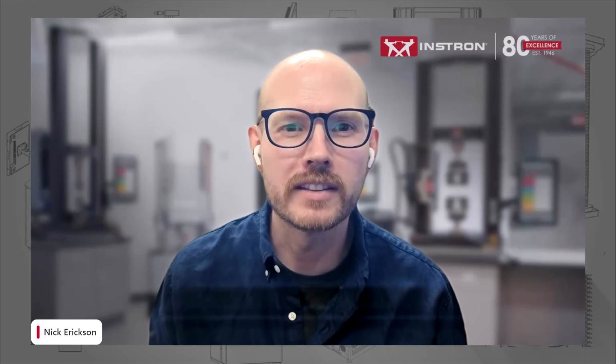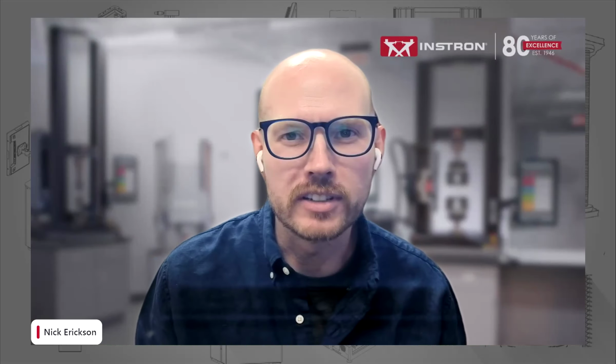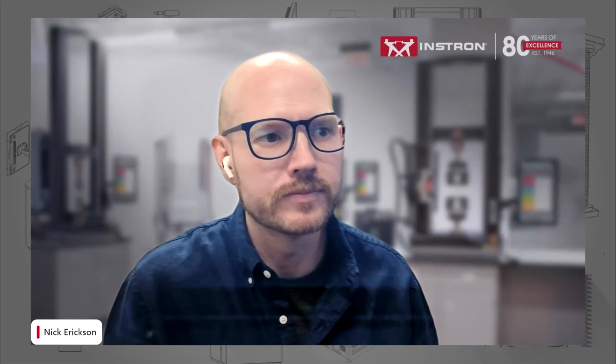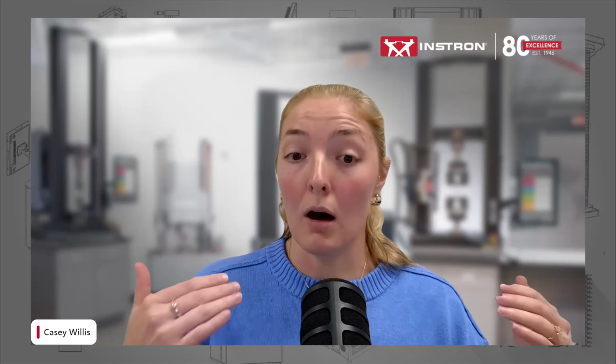Great. Next question we've got here is, what has been the best practice you have found for dealing with reflective materials being tested with the video extensometer? Yep. So it depends on what extensometer again that you're using. Maybe Josh can speak to this a little bit after, but the AVE3 has dynamically adjusting lighting. So it'll optimize the amount of light to make sure that you're getting very good illumination of the mark that you have on your specimen.